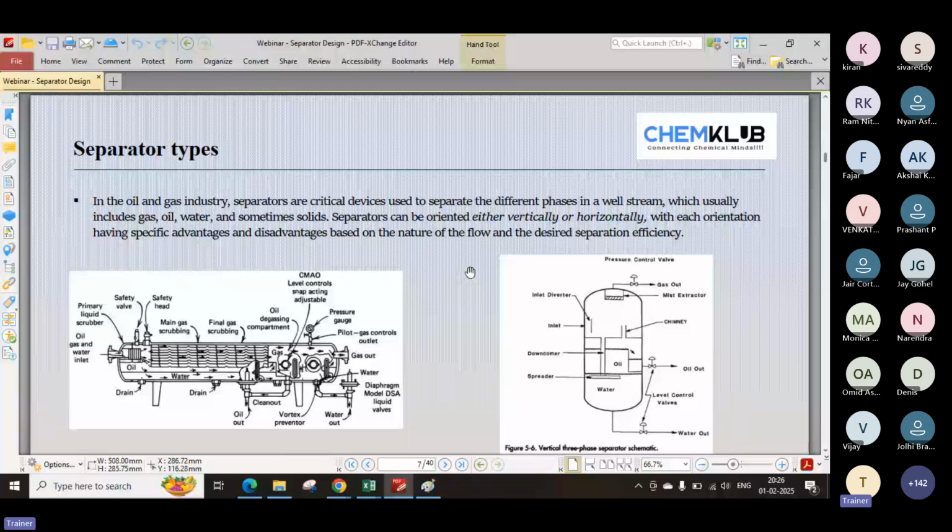At the same time, we require separators towards the compressors. Each compressor stage inlet is attached with a separator which separates any liquid particles going to the compressor section. If a higher volume content or saturated gas with enrichment of liquid particles goes to the blades of the compressors, then it will damage the compressors.